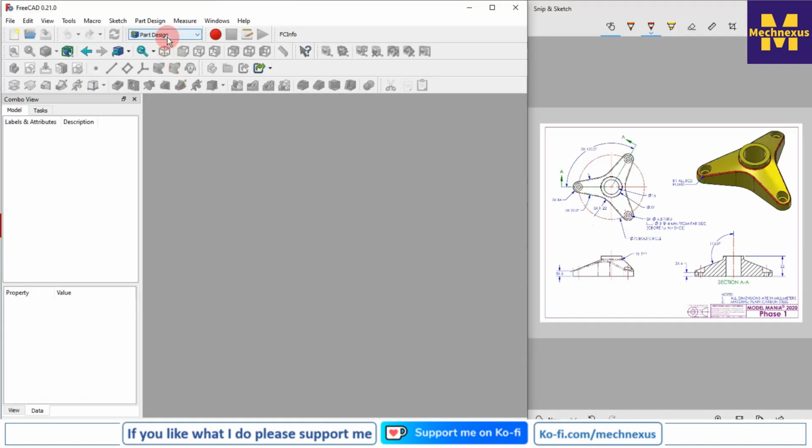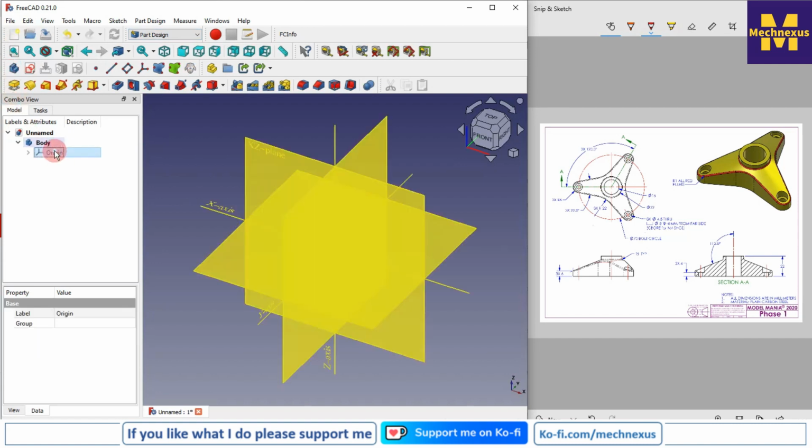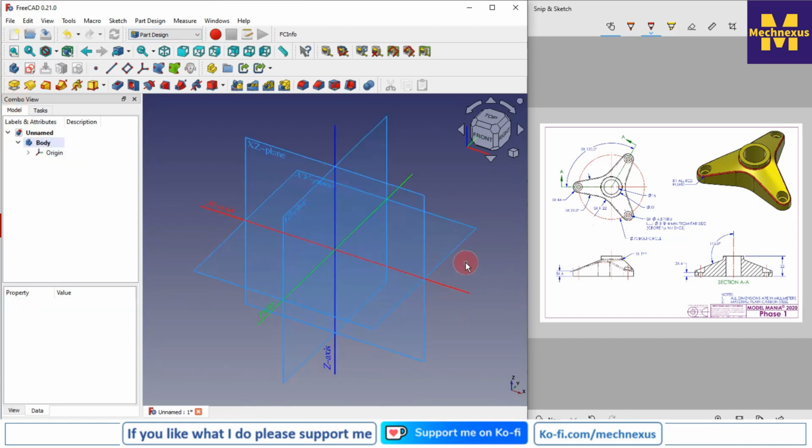So here I have activated the Part Design workbench, and I will create a new file, and first I will insert my body and then select the origin plane. So before proceeding further, we will understand our model, and according to that we will create our first sketch.